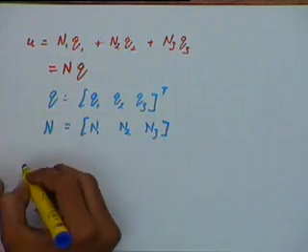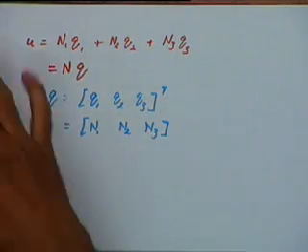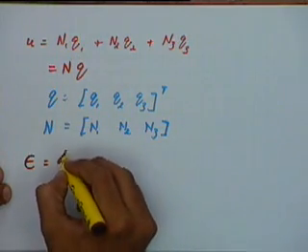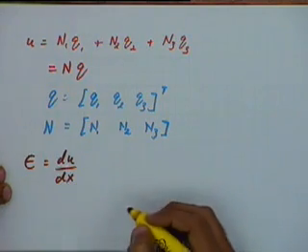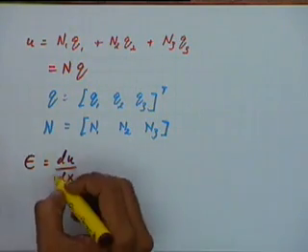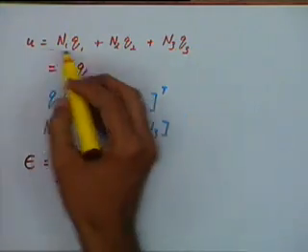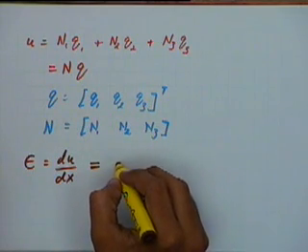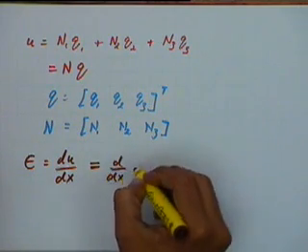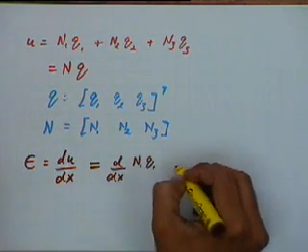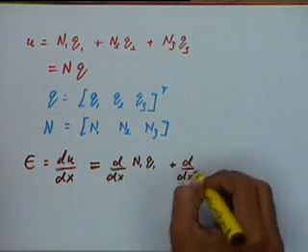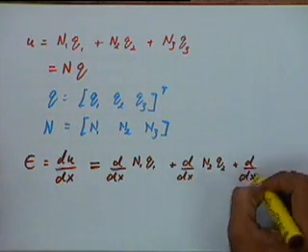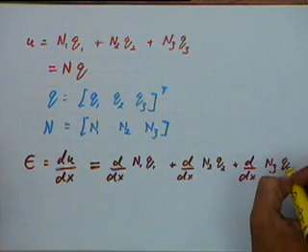And the next thing is in one dimensional elements, the strain epsilon is given by du by dx. So du by dx, if we take up this expression, it will be d by dx of N1q1 plus d by dx of N2q2 plus d by dx of N3q3.